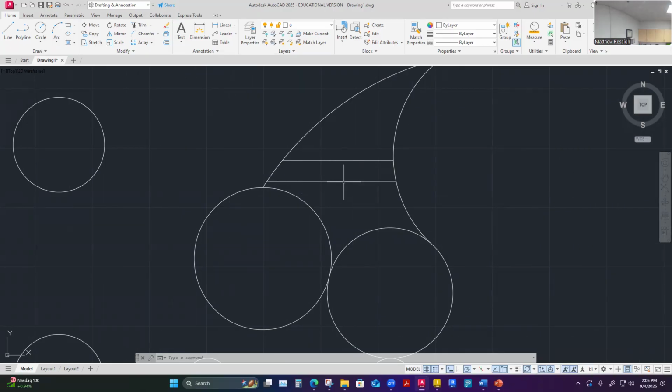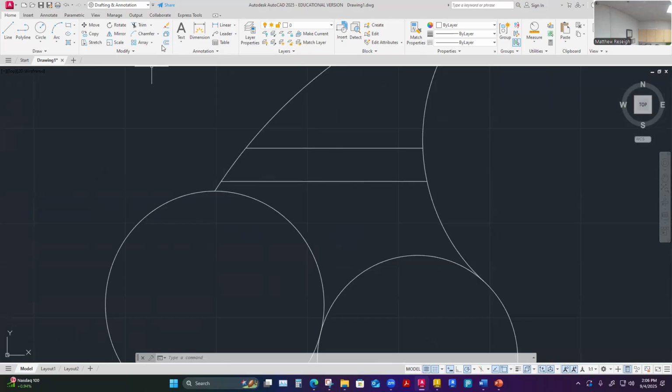So choose it and first specify options. I like this. I wish the fillet and chamfer commands showed dynamic input like this, because it's obvious that the first thing I need to do is specify a distance. And a lot of times when I'm offsetting stuff, I do know the distance that I'm offsetting.